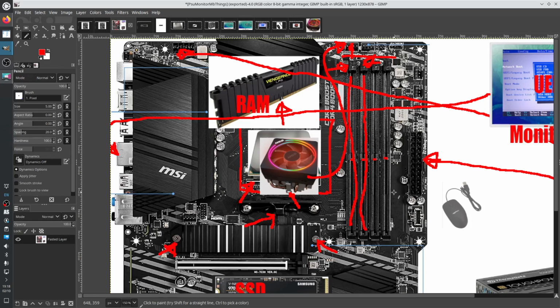So it will generate as little heat as possible, because it has a metal lid on top of it if you don't have the cooler, and this lid dissipates some heat, but a really small amount of heat. So the CPU will throttle down and use an extremely small amount of energy, such that it creates an extremely small amount of heat, which can be dissipated by its metal lid.